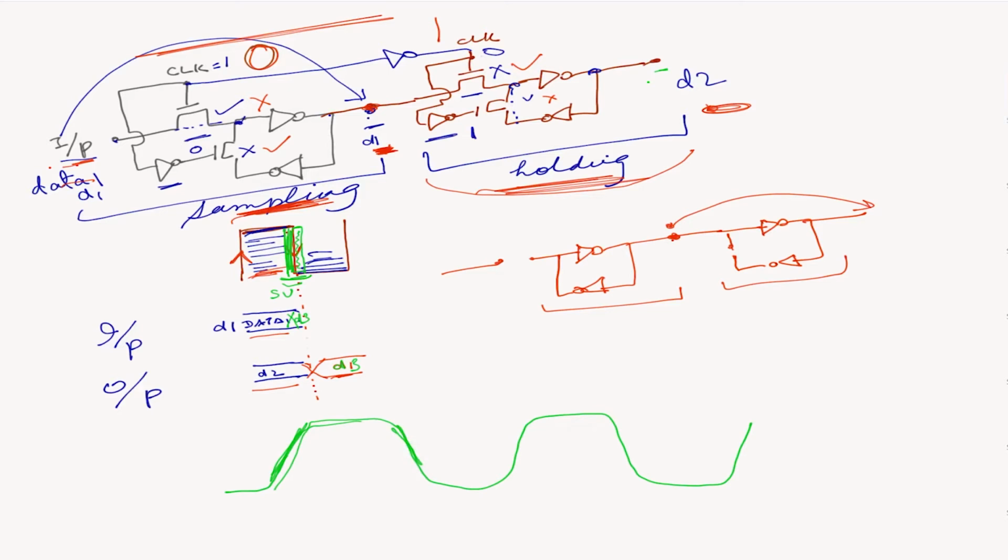And while the clock is changing and our circuits are sensitive to the value of the clock, we don't want to change anything, just some time before the sensitive edge and some time after it. So the time before is setup time. The time that you hold it after the edge is called hold time. Okay, so hopefully that explains flip-flops.